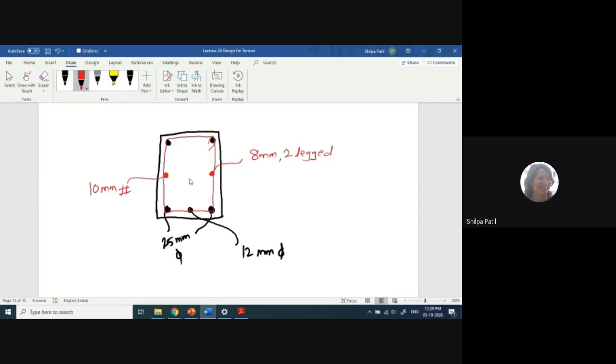Okay, and this is provided exactly at the center, between the two reinforcing bars, exactly between the two. So 500 minus 50 on both sides, 400. So this will be half of 400. So this is 200 and this is also 200. Okay, is it clear, everybody? And the bars in the compression zone, what is the diameter of it? It is 25. We'll consider 25 only because for x1, y1 calculation we have taken 25 only.